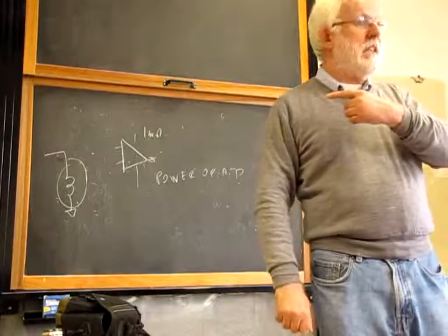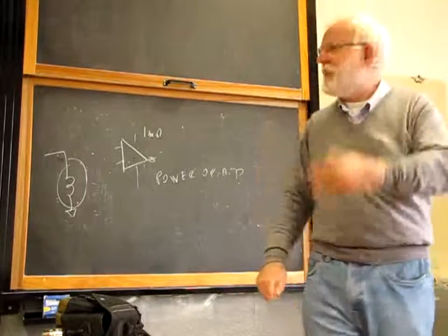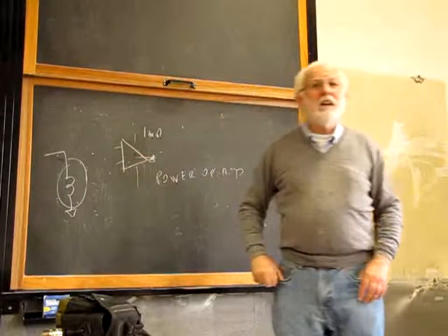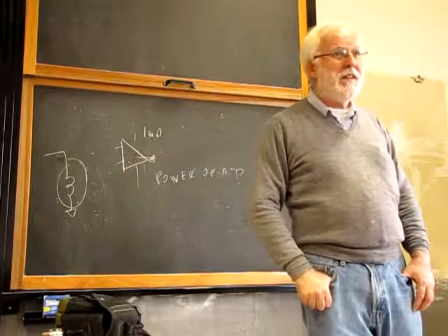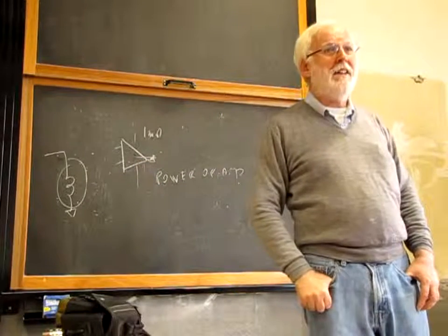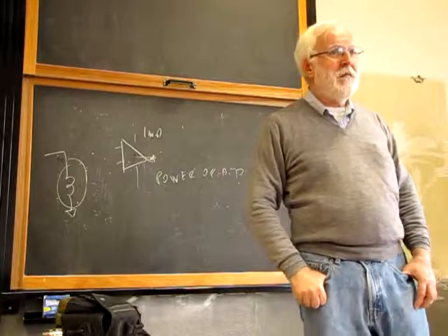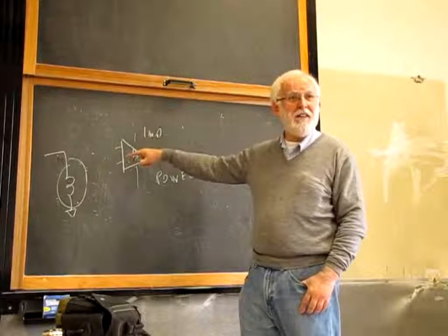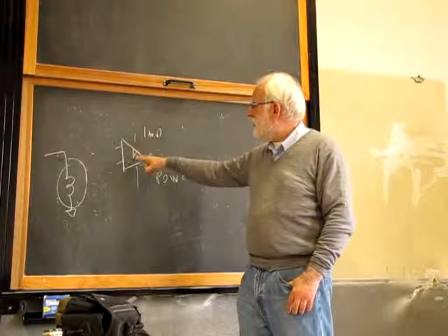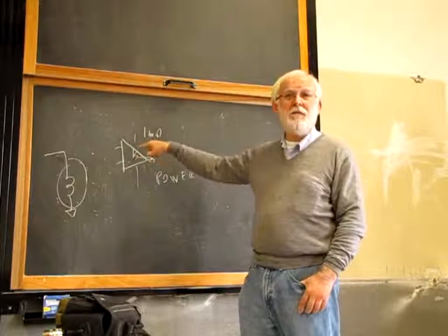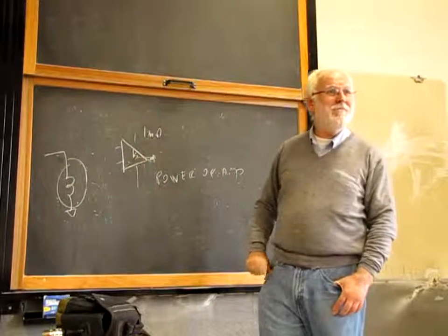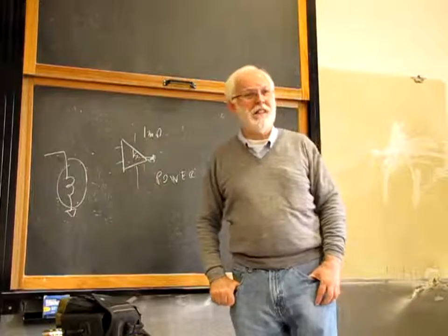Is it still an inductor? Yes, it is still an inductor, but unfortunately an op-amp that is able to supply amps on its output has a very bad efficiency, because op-amps usually have a linear amplifier in them. So this op-amp will just give you all the losses that you try to avoid. So no way to use synthesized inductors.